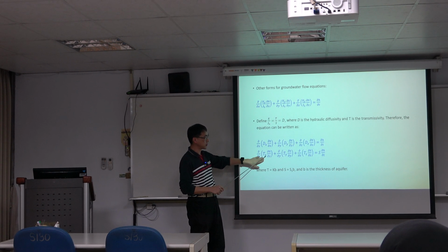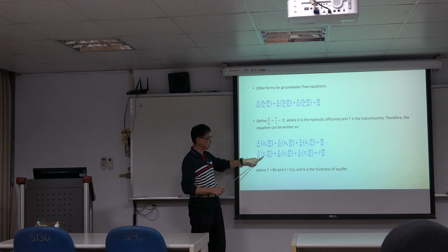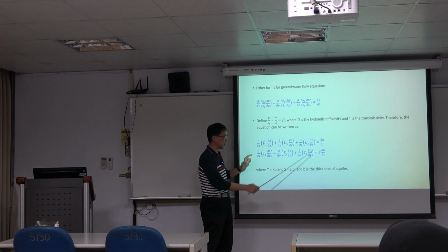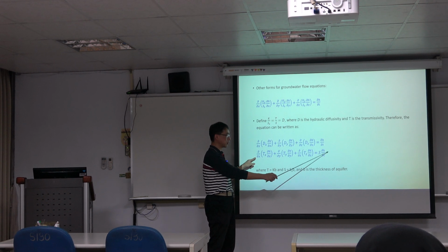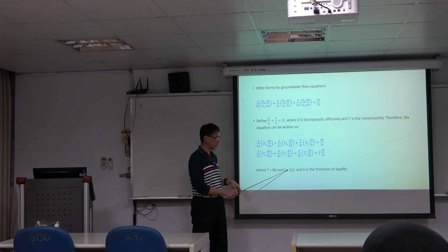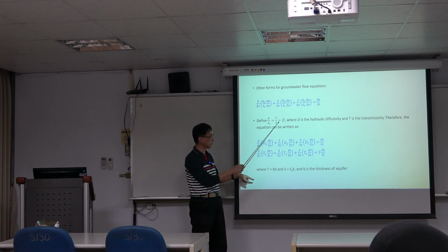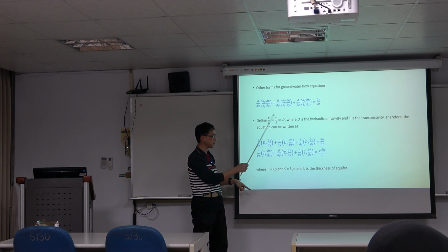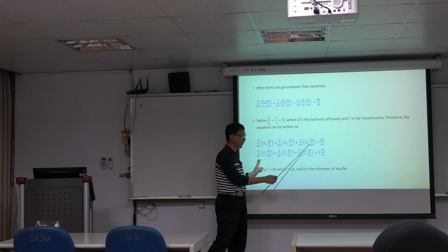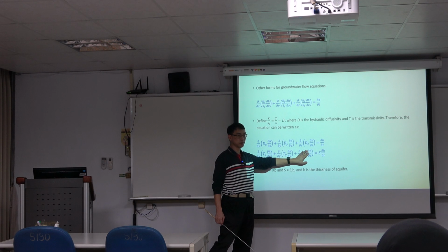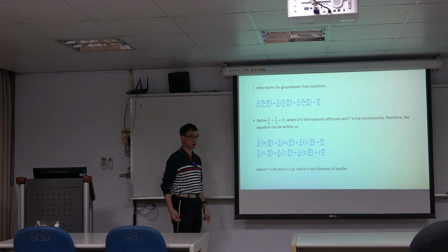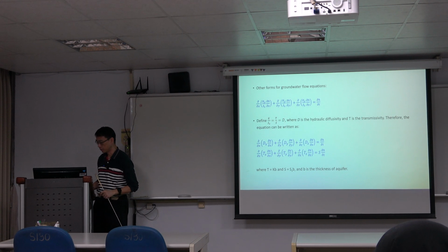And if you're using a TS system, it becomes like this. You can substitute T and S to replace K and Ss, so they become T and S. And this kind of equation is used for pumping tests or test solutions. And because we know T equals Kb and S equals Ssb, you can input that, and you can see that the b value is eliminated, so they become the same D value. Although you can write it down in this format, in a test solution we do not have the Z direction. We only have horizontal movement, so we have Tx, Ty, and S values for the test solutions, because we only assess the horizontal movement.